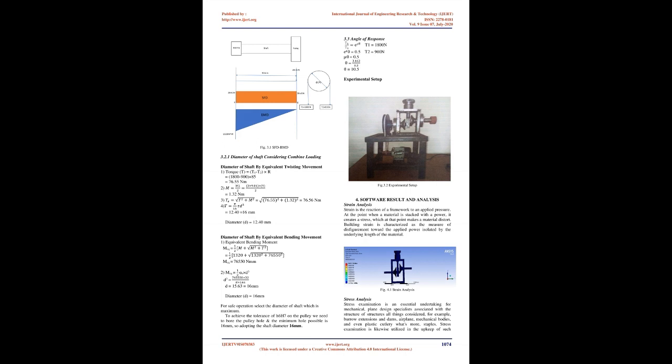As the ball is kept in an oil casing, the average percentage of slip, power loss, and level of noise produced is minimized. 1. To reduce the speed and torque. A lock nut mechanism is attached to the ball assembly; as the nut is rotated clockwise, it lowers the ball, hence the speed is reduced due to more radial distance through the periphery of the ball, and the speed and torque are transmitted to the output shaft. 2. To increase speed and torque. As the nut is rotated in an anti-clockwise direction, it moves the ball upward, and as the discs are eccentric, the radial distance of rotation through the periphery of the ball is reduced, hence the speed is increased.